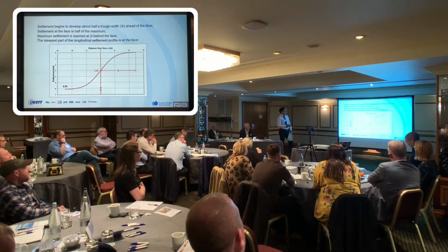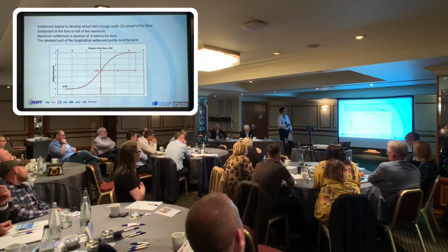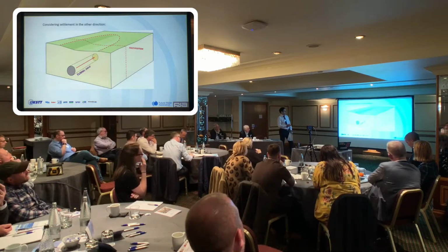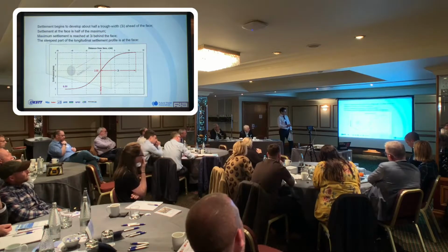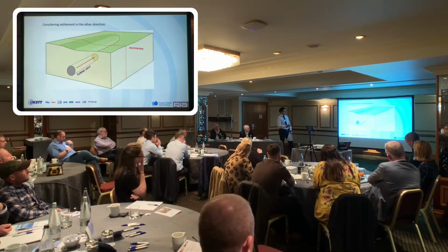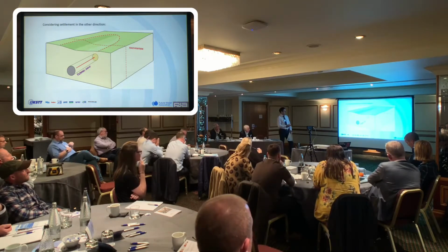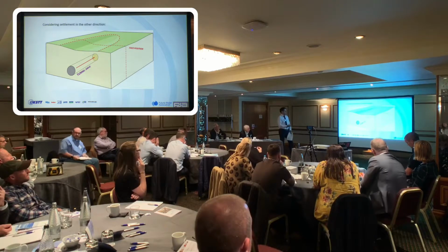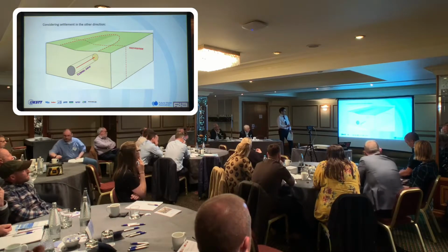Again, this is the inflection we talk about where the settlements may start to occur. So the trough width advances ahead of the tunnel drive as material falls into the void behind it, so to speak.